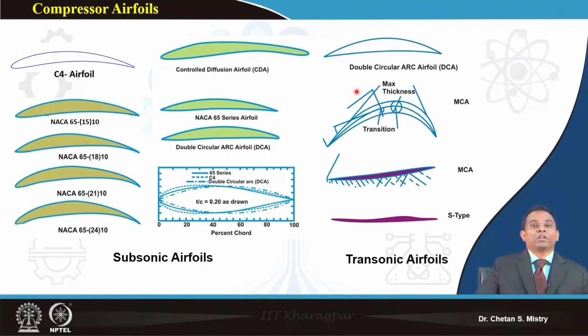So you will be making a rotor that has different kinds of airfoils. When you go for the fabrication part, it may be more challenging to fabricate those kinds of blades. Then again you need to reiterate your design. Mostly for a high bypass ratio fan, you have subsonic airfoils near the hub region, and transonic airfoils near the tip region or shroud region. For high speed LP compressors, throughout the span they may go transonic. And for the high pressure spool or high pressure compressor, most of the stages go subsonic.